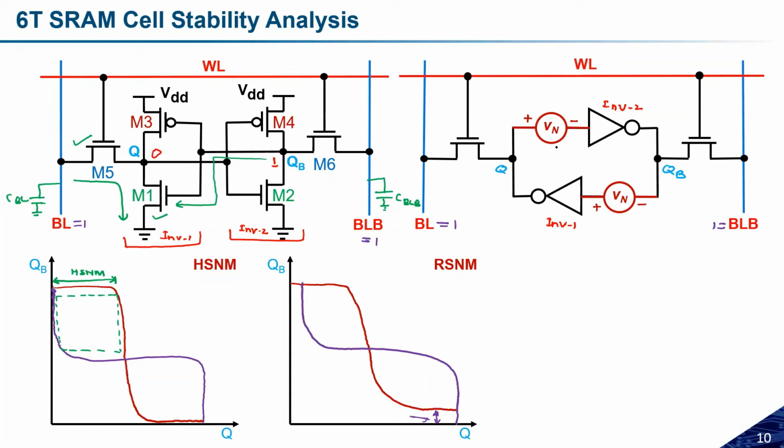Because Q was at logic 0 and QB was at logic 1, we are increasing the positive voltage at Q. What it means is that it will try to change the logic; the input of inverter 2 will become more positive than before, and vice versa. If I keep on increasing this voltage, which is nothing but the noise voltage, then after a certain voltage...